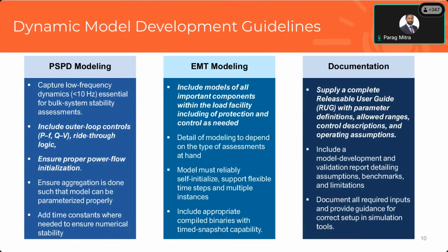Generally, when we develop positive sequence models, the high frequency loops are always considered to be stable. What we do is we reduce the stable system to algebraic equations, and that's how we are only able to represent the slower frequency dynamics, whereas the high frequency dynamics are all considered to be stable. Now that assumption holds in many cases, but if it doesn't hold, that is when we switch to EMT modeling.